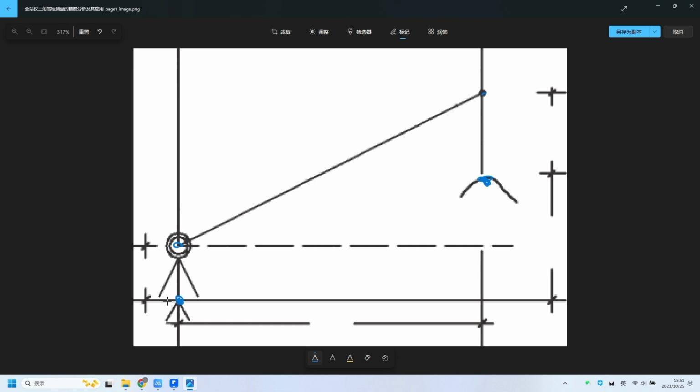If we set up stations at each point, according to your project requirements or accuracy requirements, it can be observed unidirectionally or in opposite directions, because it is similar to the back and forth measurement of leveling. We can observe at this point according to the direction of the wire, so that the height difference between the 2 points can be observed. Then the next time we are at the third point, the instrument can be directly installed at the third point, and the middle point can be left unused. Then, we can observe the height difference.